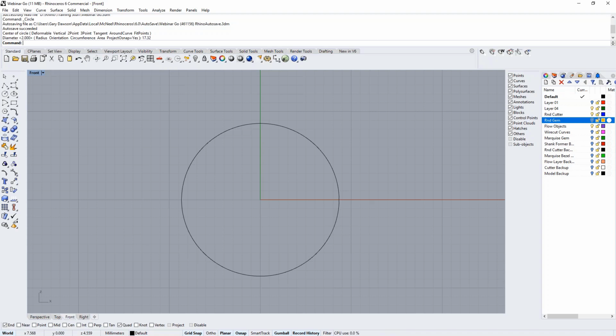Right, right. Well, that's pretty exciting though too. But the thing is that blending surface and filleting, I mean, fillet is a command in Rhino, so it takes like a second to fillet surfaces. But for more complex surface junctures, blend surface tends to work a lot better, it seems like, for me. But it doesn't take that much time, so you can do all of this right in Rhino.